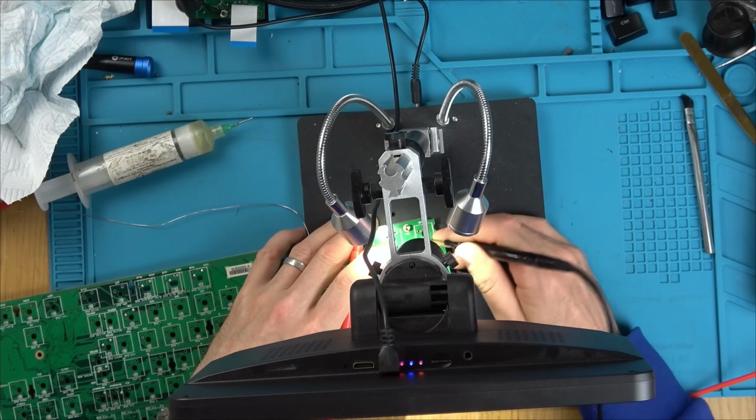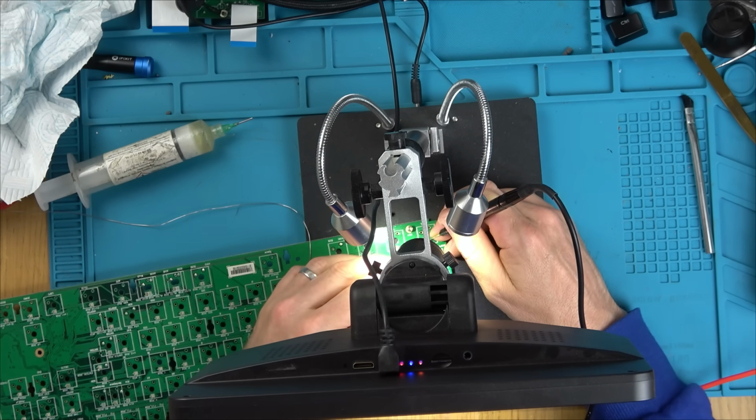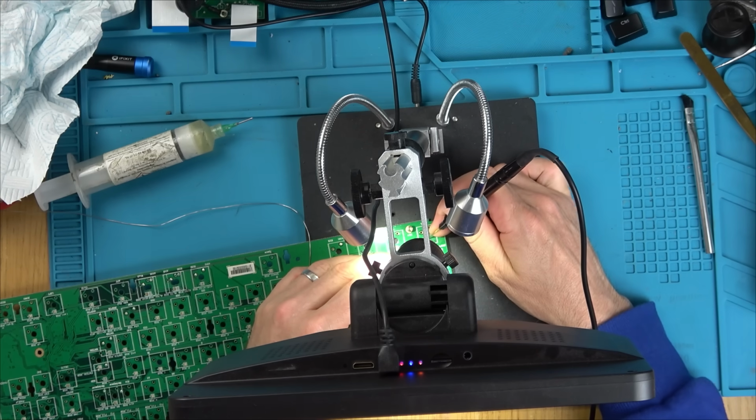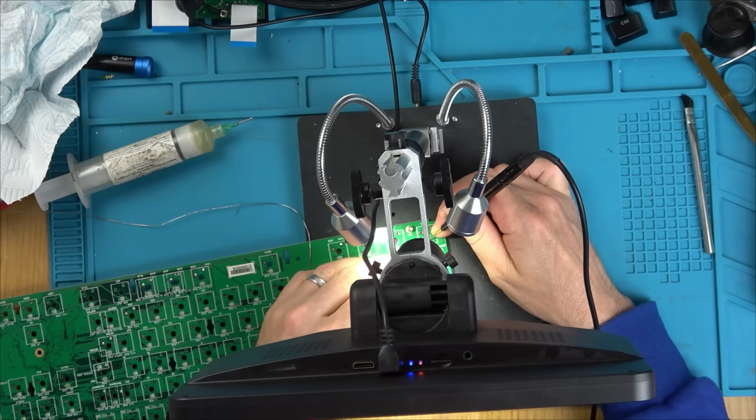Bottom line is that I scrape all around these LEDs. It's the LEDs that have failed. Clearly it's been water damaged. There's corrosion all around the pins, so the LEDs are not working. So what I do is I get my bench power supply, I set it to a very low voltage, and we should have 3 different colours on here. RGB, red, green and blue. All those 3 colours will make up every single other colour.